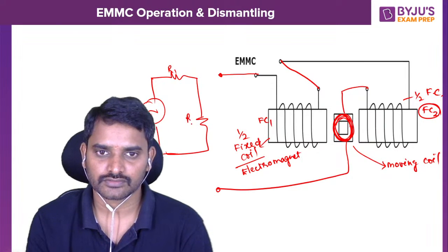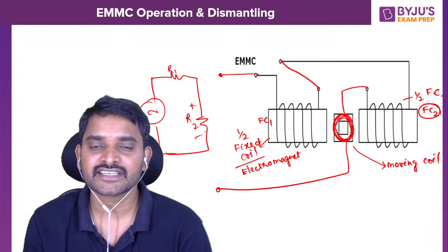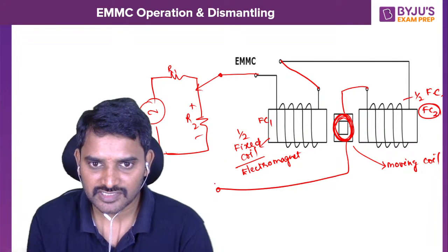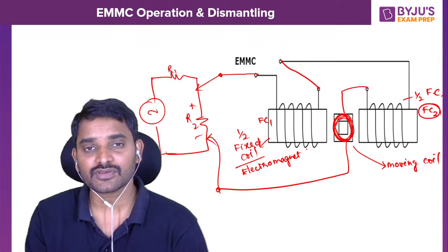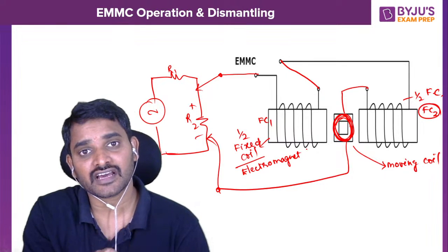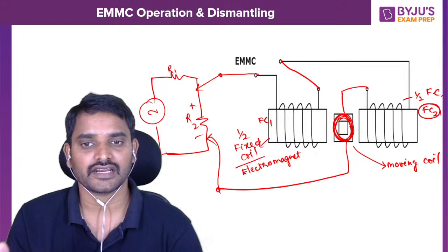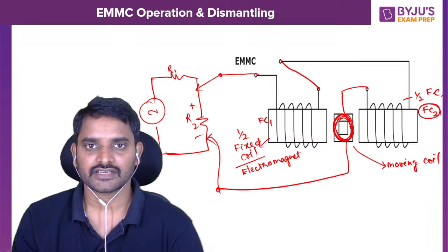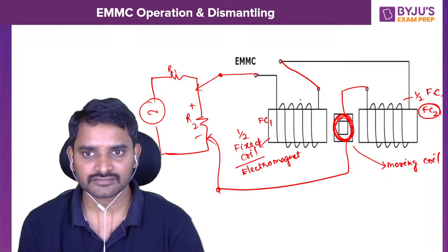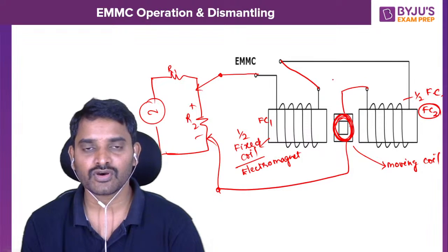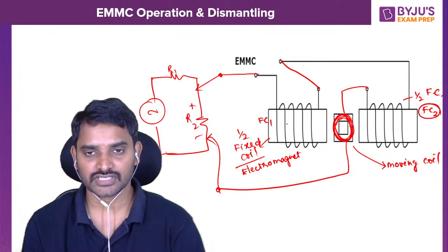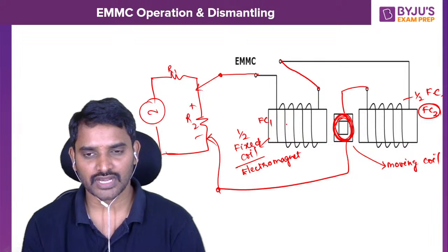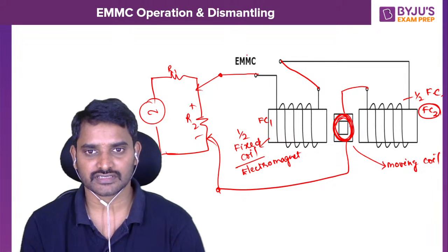R1, R2. Now if you want to measure the voltage across R2, connect these terminals at this point. That's it. So this is going to behave like a voltmeter, and if you connect this meter in series with R1 and R2, then that is going to measure current. All right. So there are some names for these 4 terminals, I'll give you those names also, but I just wanted to add one more point at this moment.